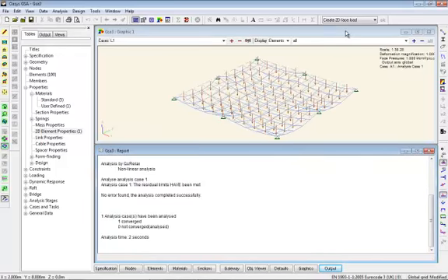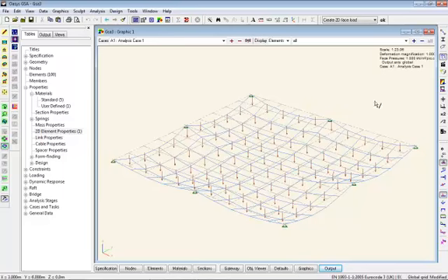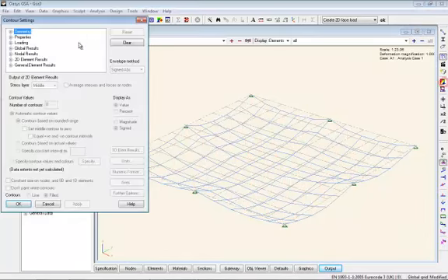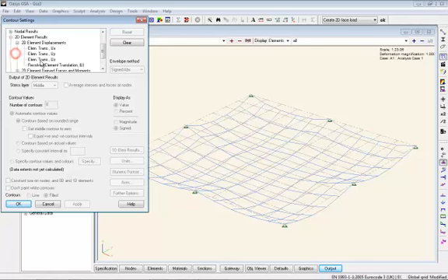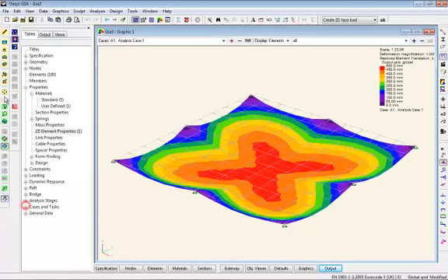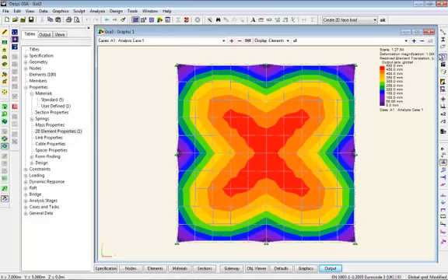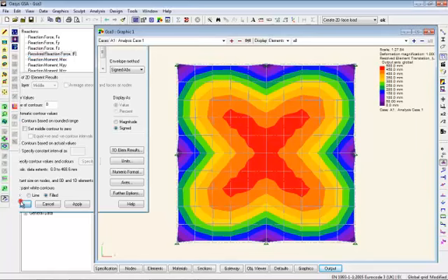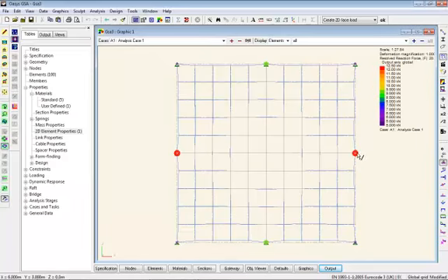And there we have the deflected shape. Now this looks quite symmetrical. Leave those on. Let's look at the displacement. And you see, yeah, it's reasonably symmetrical. Not entirely symmetrical, but in the main. But if I change the contour results to the reaction forces, you'll notice we're actually getting far more reactions at these points than these points, even though the structure is symmetrical.